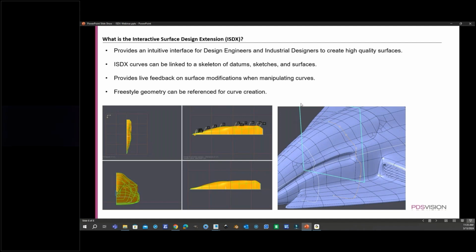You can say, hey, let's unlink this point along the curve from the mesh so that way we can move it wherever we want. Okay. And also that's great too if you want to just blow away the model in the end. So say you're like, hey, we don't need this Freestyle mesh anymore. Let's just delete it from the model tree. If you unlink all those points along the curve from the mesh, you can do that.